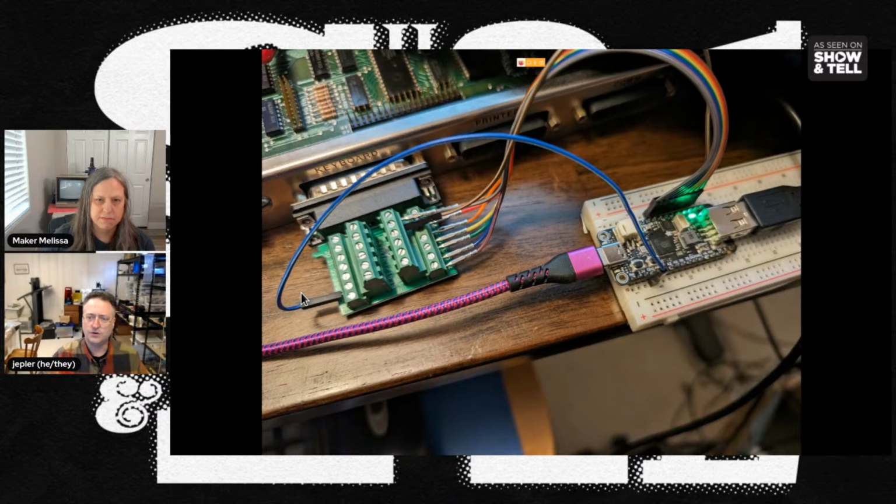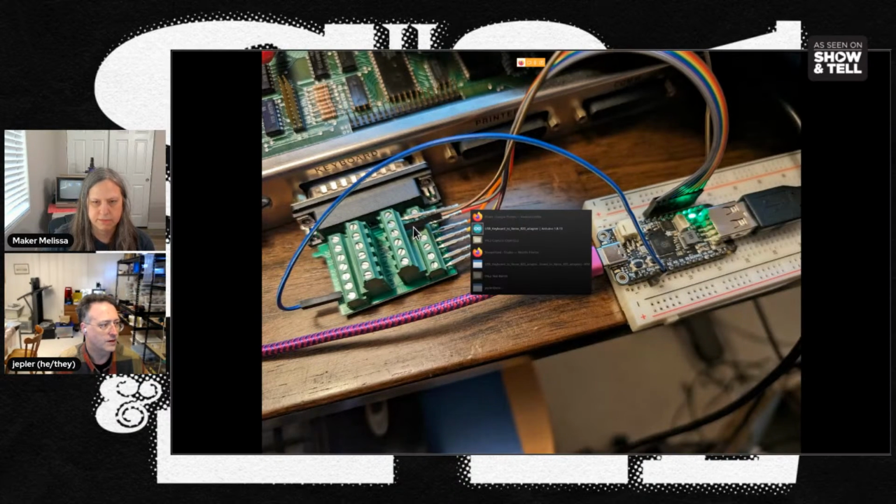And this here is a photo of the wiring. So here on the port marked keyboard, it just takes 8 bits in, that's 1 through 8 here, and then the 9th is a strobe to say there's a key ready to be received. And then the CP/M computer, or the firmware on the Z80, has to notice that signal coming in and grab the key and do whatever it does with it. But this was all really well documented in the old manuals, because computers in those days were very well documented.